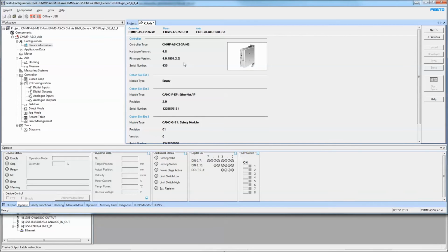So when you're using a generic module, the first double integer on the older firmware is the header information. So you need an additional 4 bytes. So this version 2.2 that I've shown you in this video drops that header information. So at this point, I'm just going to show you that.